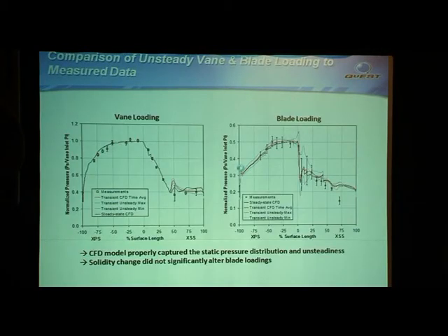So in terms of validation, there were pressure data taken off for both airfoils, both the vane and the blade, for us to compare to. In terms of the vane loading, so this is pressure along the vane surface. On the suction side and on the pressure side, you can see that the model was in good agreement there.